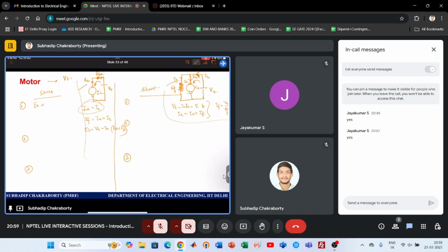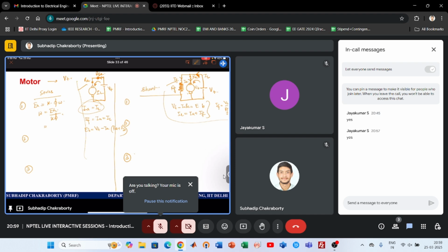So what is EA? EA is K phi omega. What is omega? Omega is EA by K phi. What is EA or EB? V minus IA RA by K phi.